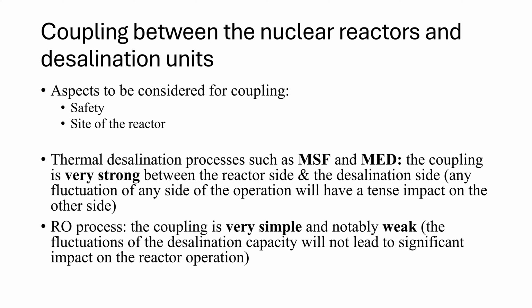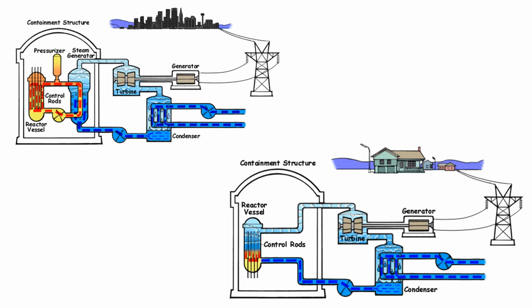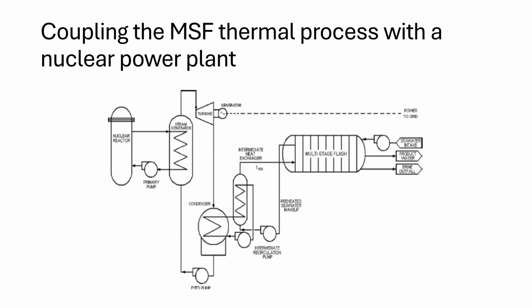A lot of studies were triggered to evaluate the feasibility of these options, and they came to agree that it is cost effective and produces clean energy, with no greenhouse gas emissions. This is where I wanted to tell you about safety. When you consider coupling desalination with a nuclear plant, you have to put intermediate steps between the condenser and the steam coming from the turbine.